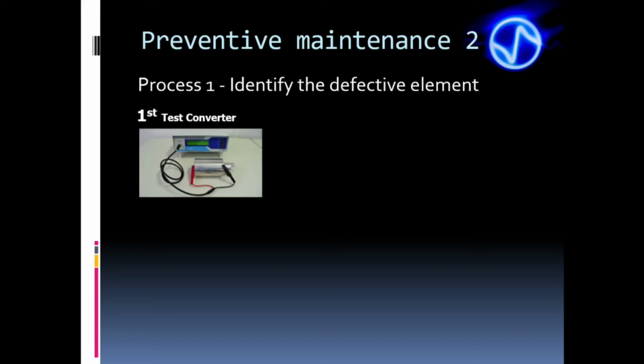The first criterion is the quality factor QM, reported by the TRZ analyzer. For the converter alone, it must be greater than or equal to 250. To explain this in a simple way, QM is the number of times that the tested element vibrates by itself by inertia after turning off the generator. Therefore, the higher the QM, the more easily and efficiently the stack vibrates.